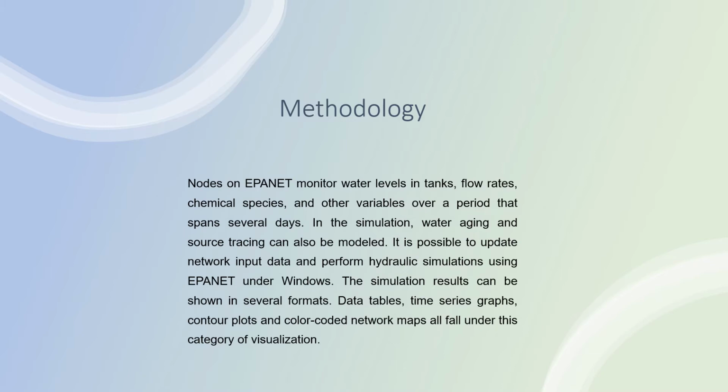It also contains a state-of-the-art hydraulic analysis engine, and the nodes on Epanet monitor the water levels in tanks, flow rates, chemical species, and other variables over a period that spans several days. In the simulation, water aging and source tracing can be modeled.